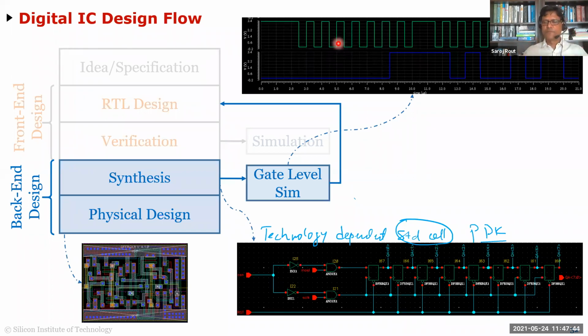So even in a full custom design, where you're drawing in layout, you still need a layout tool, right? A layout tool is part of physical design. So that's the bare minimum you need. You cannot start drawing layers by hand. They used to do that when they were doing single transistor design. Obviously, you can't do that right now. So even for a very simple full custom layout, you still need a layout editor, and that tool is for physical design.